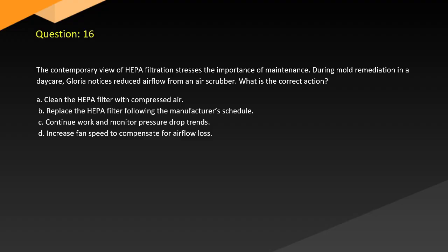Question 16. The contemporary view of HEPA filtration stresses the importance of maintenance. During mold remediation in a daycare, Toria notices reduced airflow from an air scrubber. What is the correct action? A. Clean the HEPA filter with compressed air. B. Replace the HEPA filter following the manufacturer's schedule. C. Continue work and monitor pressure drop trends. D. Increase fan speed to compensate for airflow loss.